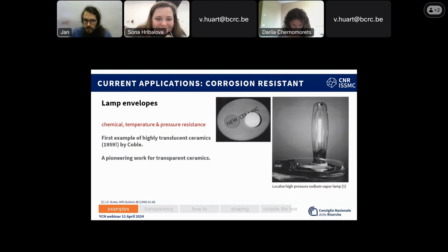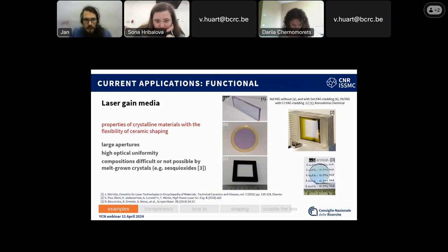And this is just an example of how important the microstructure is, for example, for the use of hot isostatic pressing, which is quite common if you need really high transparency. If you start with microstructure with small grains and pores that are at grain boundaries, by hot isostatic pressing, you might be able to remove those. If already in the pre-sintered piece you have pores inside grains, they're most likely going to remain. They're really difficult to remove, if at all.